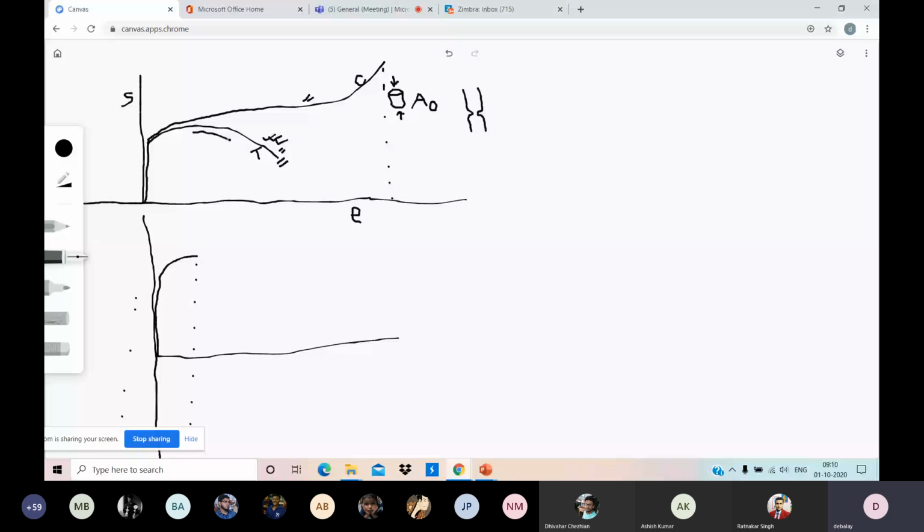Because the material continuously strain hardens, as we have explained before. But due to necking, the decrease in cross-sectional area is so rapid that strain hardening cannot be maintained. That is, true stress increases even if your load comes down. You remember the previous discussion that we had?